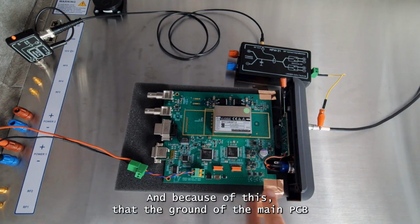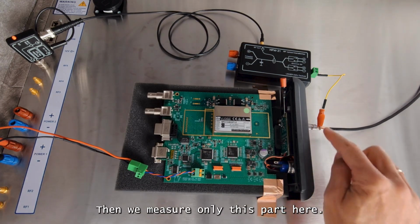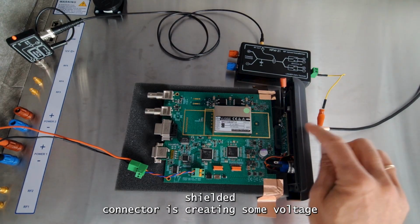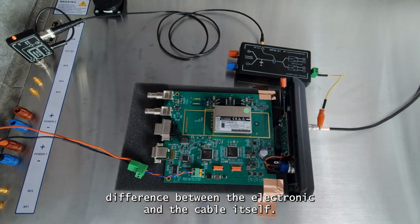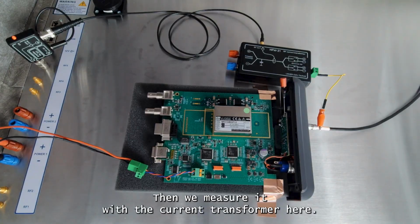Because of that, this ground of the main PCB is connected to the reference plane, so we measure only this part here. And if this shielded connector is creating some voltage difference between the electronics and the cable itself, then we measure it with the current transformer here.